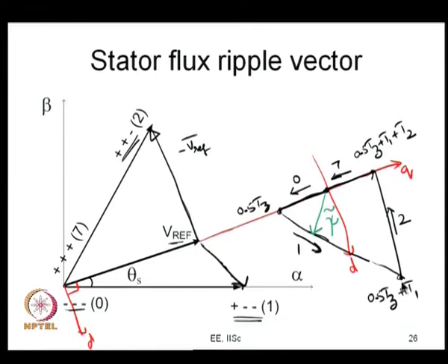And when you reach here, it is 0.5 Tz plus T1, and from there vector V2 is applied for time T2 seconds and it moves here at a constant speed. This speed is proportional to the magnitude of the error voltage vector. Then it goes and reaches here, and finally it goes back and reaches this point now.